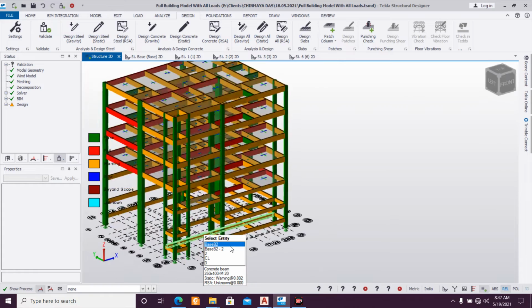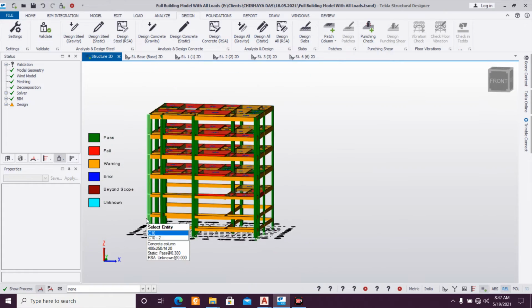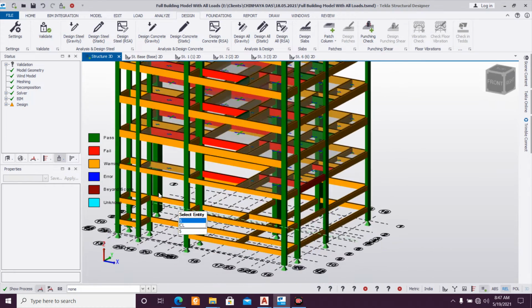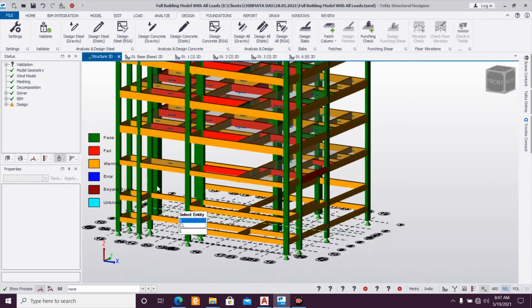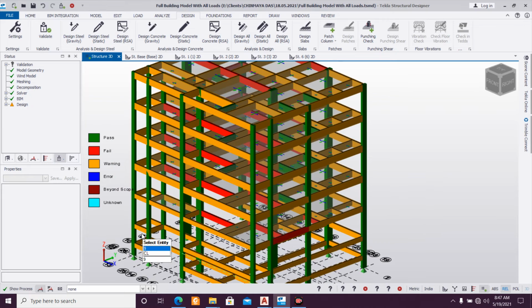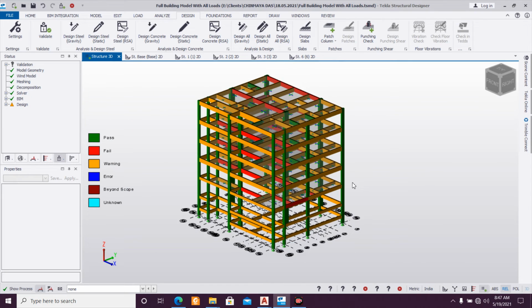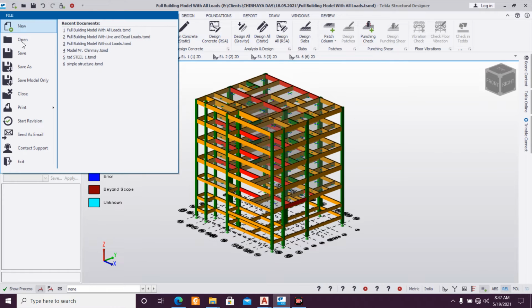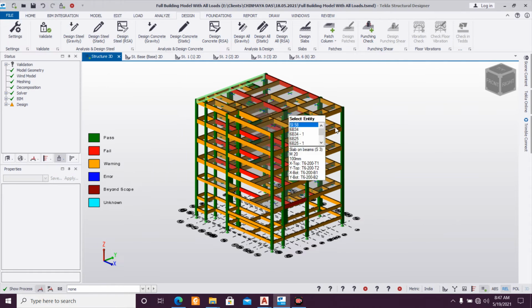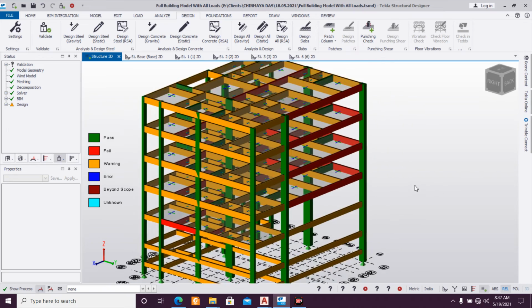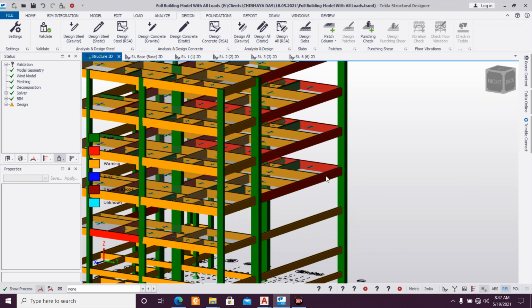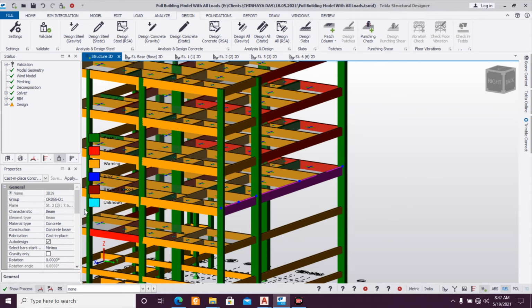So like this we can proceed with making the beams safe in all the zones here. Like this you can proceed and make the beams safe. We can also provide the foundation here. Okay, so when this is not safe, this really needs to be safe, at least the exterior beams. Let's make this exterior beam safe. So I think we need to give this a bit more width.